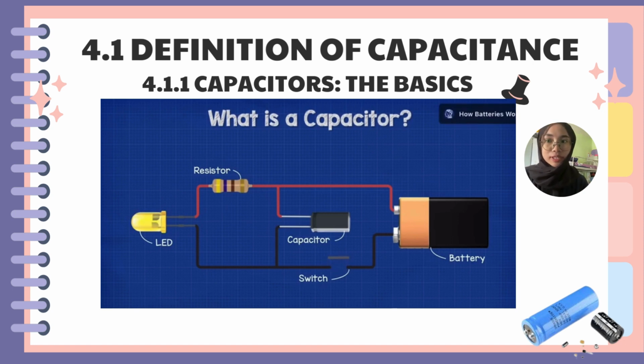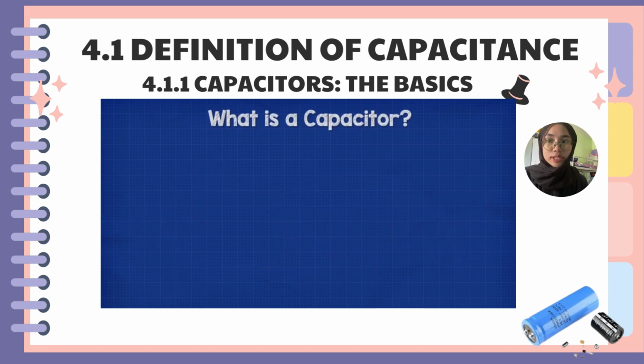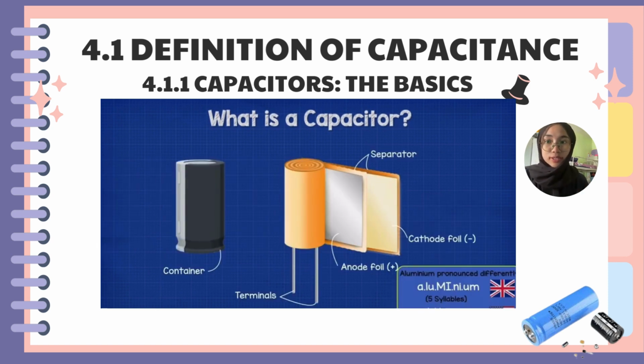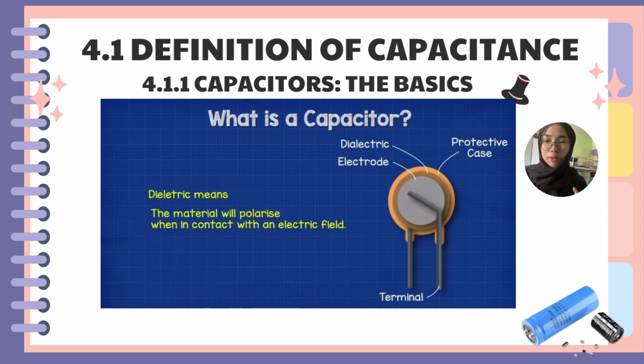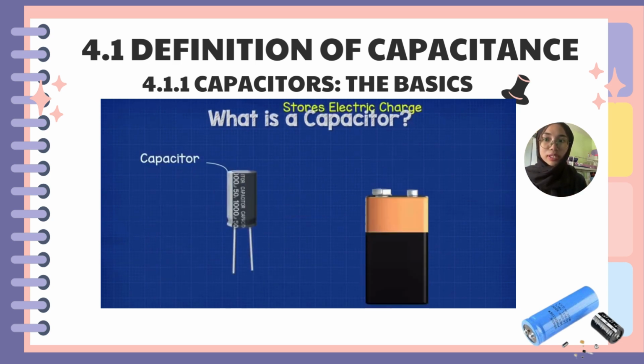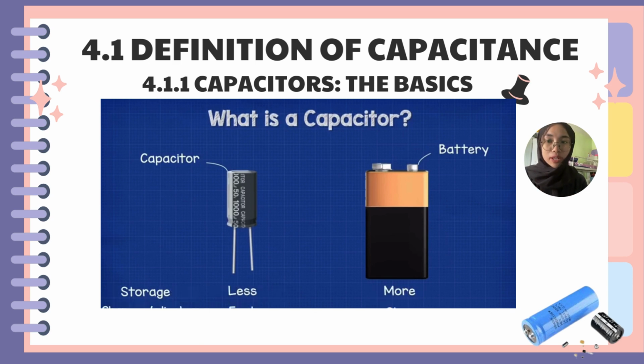In electric circuits, the capacitor acts as a water tank and stores energy. It can release this energy to cover any interruption to the supply. If we turn a simple circuit on and off very fast without a capacitor, then the light will flash. But if we connect a capacitor into the circuit, then the light will remain on during the interruption, at least for a short duration, because the capacitor is now discharging and powering the circuit.